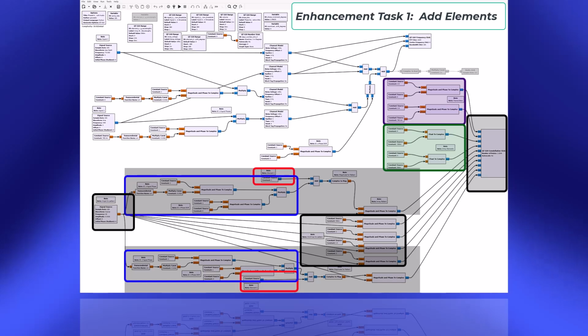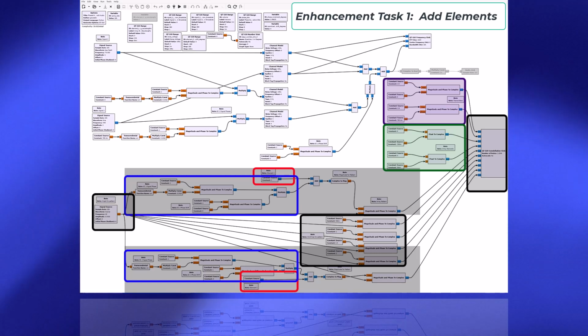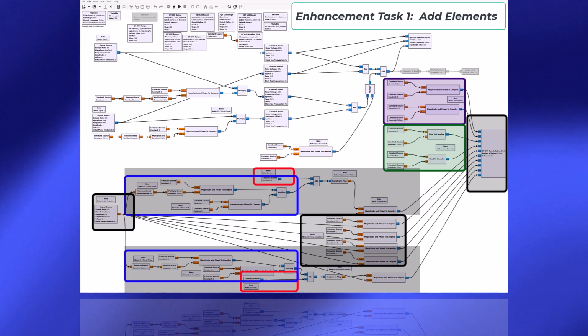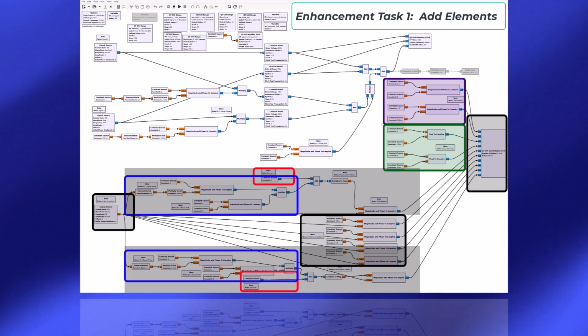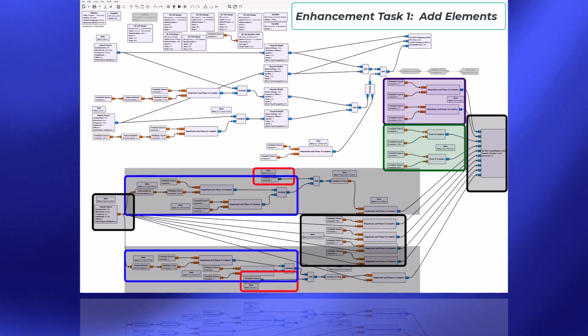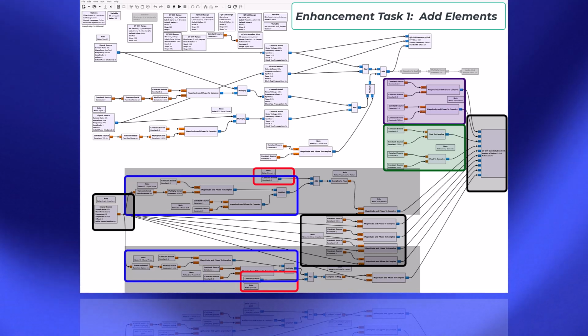If it's too high, it would result in unnecessary calculations, so you might want to change it from what you see in the example. And basically in each of these array pattern calculations, you see a constant that represents the contribution of the reference element, and that's added to the output from all these other blocks that represents the contribution of the second element with phase shift that depends on the spatial angle generated by the signal source.